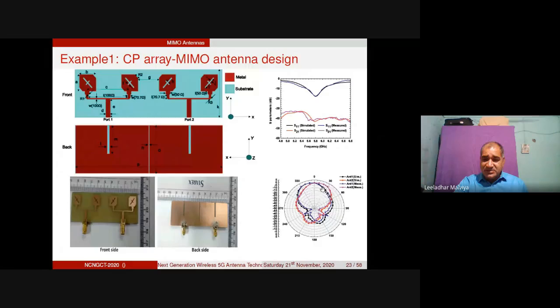And you know that these are covering minus 10 dB and plus 10 dB of the direction, right? So my question is why this discussion is important here, because the 5G requires beamforming, right? So MIMO is capable of doing the beamforming. If you look at radiation patterns, these are not too sharp here, but still plus 10 dB and minus 10 dB can be obtained here.